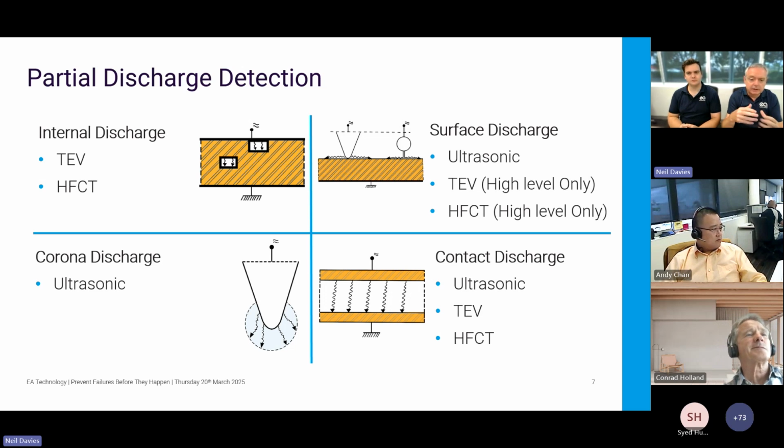The byproducts of the discharge are going to dissipate just like they do with corona, and are not going to cause too much of a problem. But it causes local noise, which can mask other things out. If you start looking at contact discharge inside switchgear, then again, it can be a significant problem. So really, it's a different type of discharge that we need to detect with that.